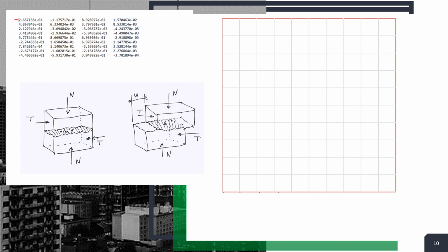Okay, this was actually a result from a shear test, and this is the principle of the shear test. The shear test is, we have a sample like this, and we have a normal load like that, P, and another normal load like this, and then we shear, that plate moves like this, and then we shear there. Of course there's a plate there, so normally we expect a shear zone here, a shear zone there. So this is where you expect it.